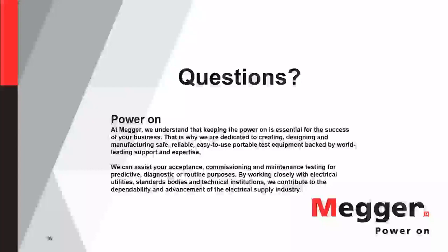So yeah, a couple of things. There's the calibration of the transducer that tells you degrees per pulses, pulses per degree, pulses per millimeter, or volts per millimeter, whatever. But then you'll hear the term conversion factor, you'll hear the term conversion table, or you'll hear the term transfer function. Like you'll look in the manufacturer's manual sometimes and they'll say the transfer function for this is, like I'll see one and it'll be a tangent function or a sine function. So they're all kind of the same thing. If you have a direct connection, you don't need it, but conversion table, conversion factor, transfer function, they're all referring to the same thing, how to convert generally an angular measurement into a linear measurement, or multiplying a linear measurement to another linear measurement because you're not on a direct connection.